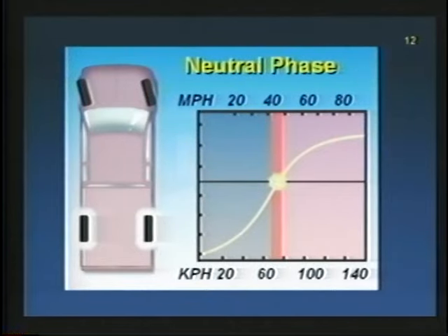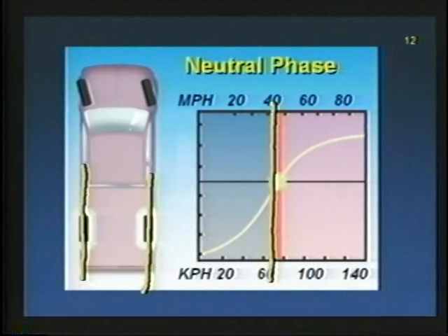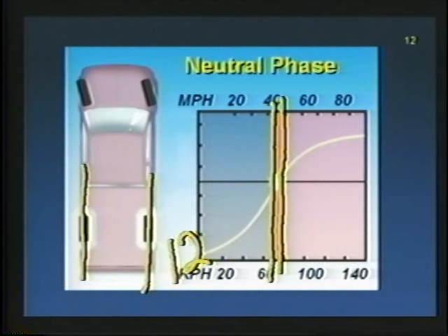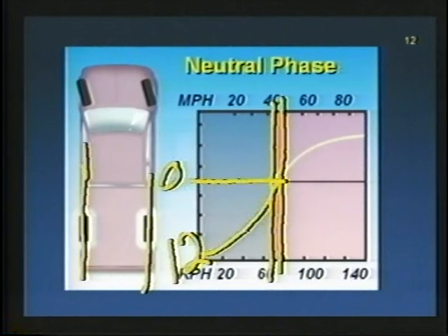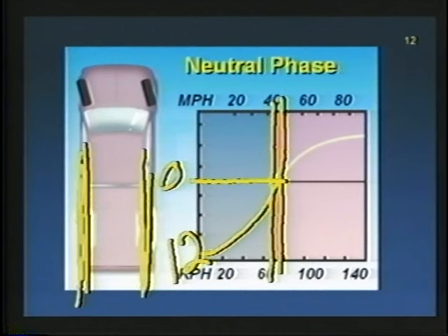All right, there it is, neutral phase. What's happening in the neutral phase? Well, we've got the rear wheels in the straight ahead position. Now, this is going to occur right around that 45-degree mark. So, like Andrew said, we've got 12 degrees in negative phase. Slowly, we're picking up speed, we're getting rid of that, getting closer, closer till at this point right here, that's 0. That's the rear wheels in that straight ahead position. Not turning them at all.